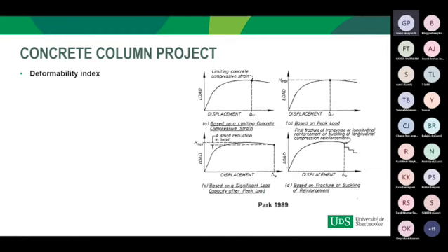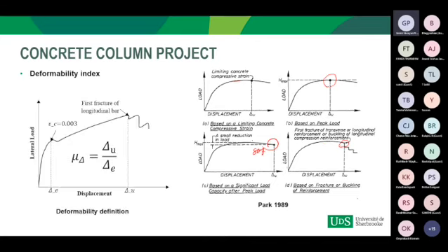The ultimate displacement has been estimated for the experimental structure, and it can be based on limiting the concrete compressive strength, peak load, a small reduction in the peak load, like generally we take an 80% reduction at this point, and first fracture of the transverse or longitudinal or any reinforcement. For our columns, only these two can be valid.